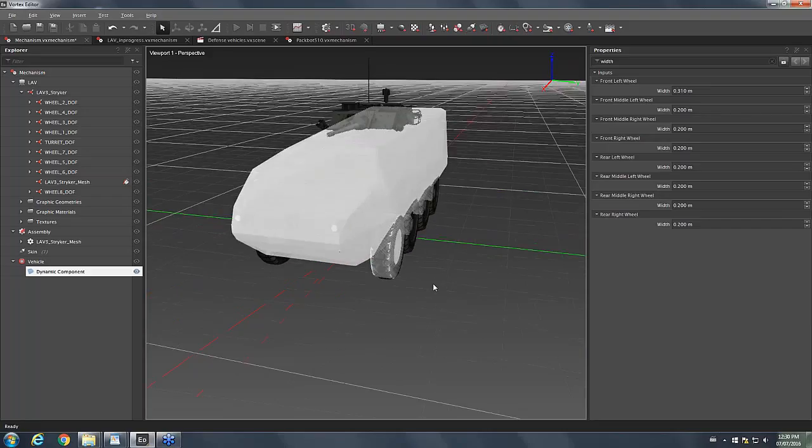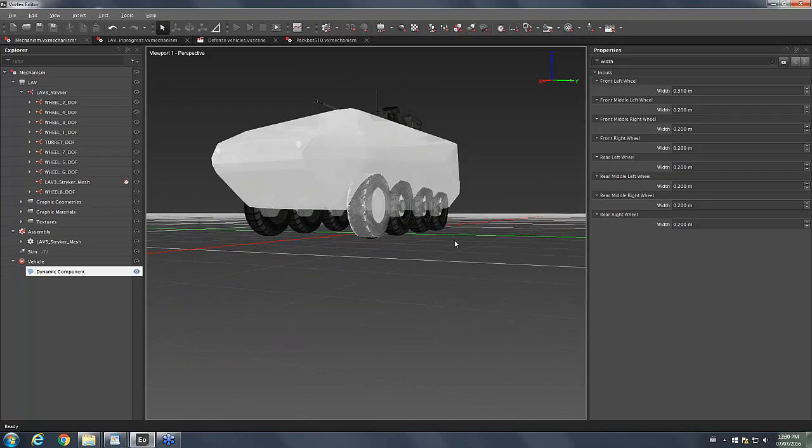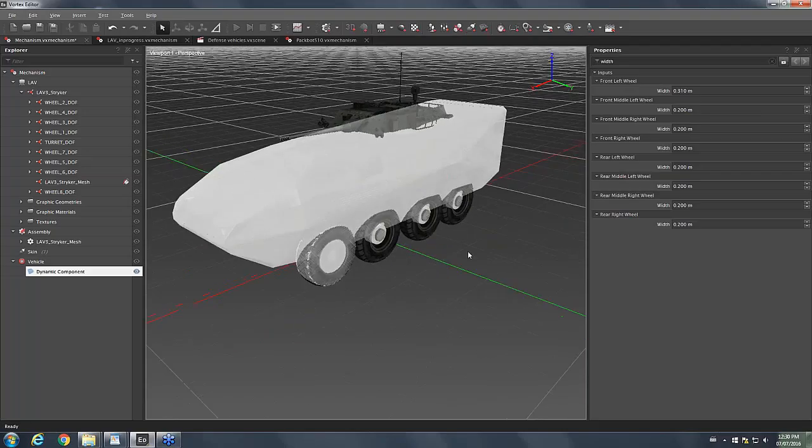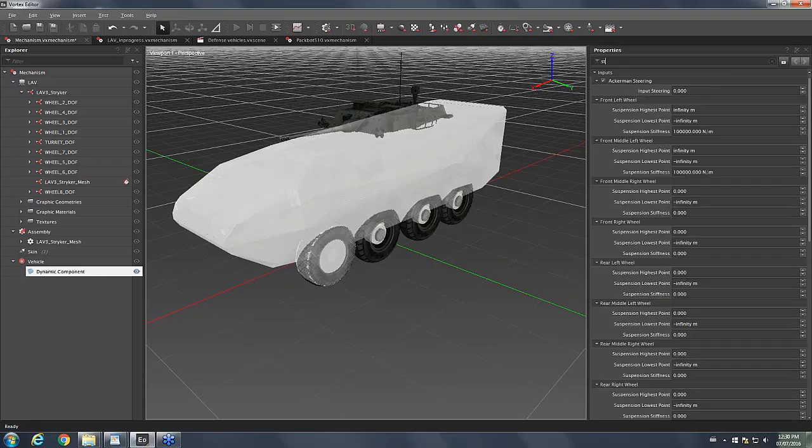You'll notice that the vehicle is oriented along the positive x-axis, and it's at the ground level. It's very important when you set your 3D model that it's oriented that way to avoid confusing the vehicle system and getting bad reference. Let's keep on going on the wheel. I'm going for the mass, so now I've got 30 kilogram, for example. And then I would repeat this for every wheel, obviously.